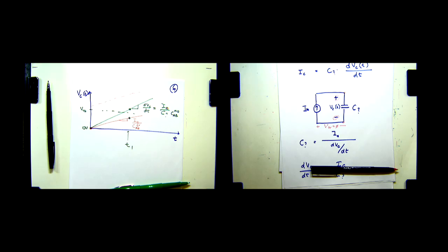In other words, we put the finger there and leave it there. The capacitance now is fixed. Then we discharge the capacitor, hook up the current source, and make our measurement. The capacitance is constant, and we make this determination: is the finger present or not. Once we're done, we start the whole process again.